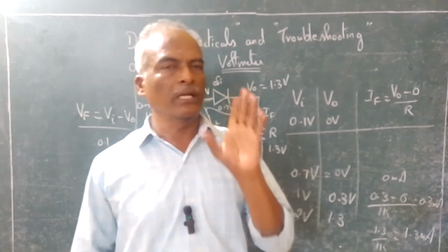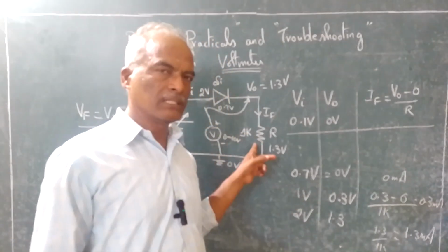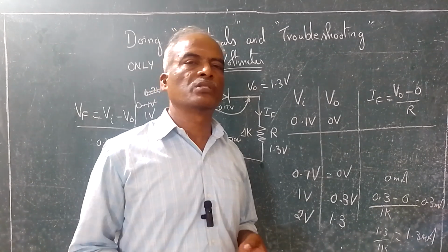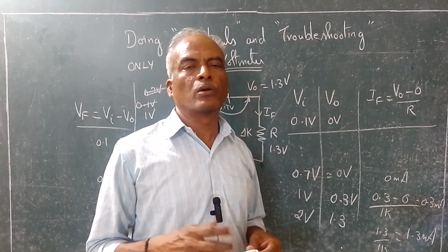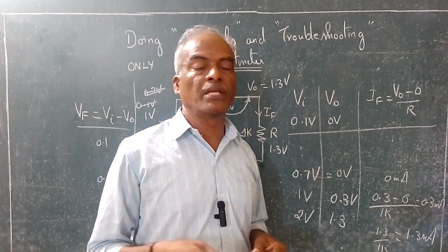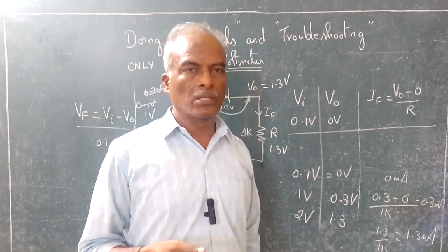So the only condition you have to remember is you must know the value of the resistance. How to find the value of the resistance? By color coding, or you can use a good quality digital multimeter, in which you choose the ohms range and find the value of the resistance.